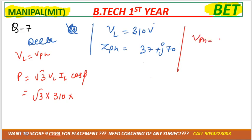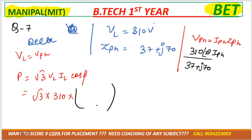So we'll have the formula VPH is equal to IPH into ZPH. So VPH is how much? 310. IPH we need to calculate, and ZPH is how much? 37 plus J70, right? So you can solve it, you can consider it as an angle 0. Then you can put the value of IL there, IL is equal to root 3 IPH, right? So whatever the value of IPH you are getting, multiply by root 3.